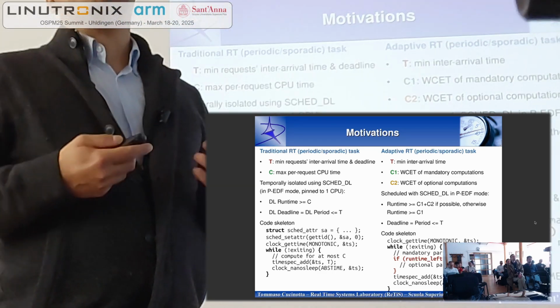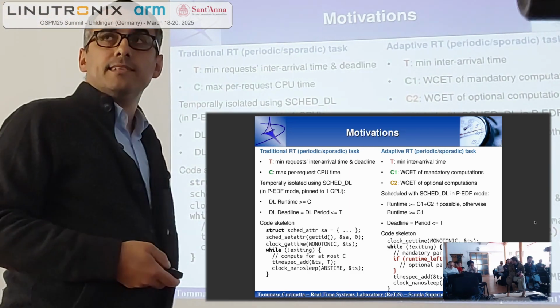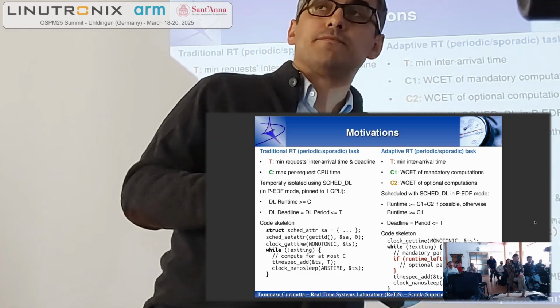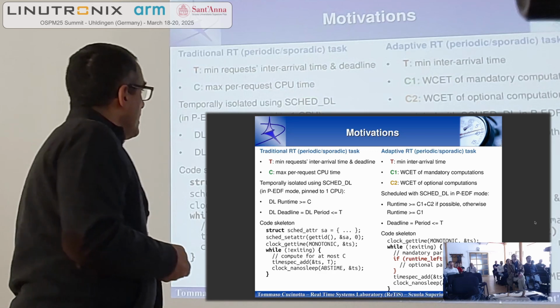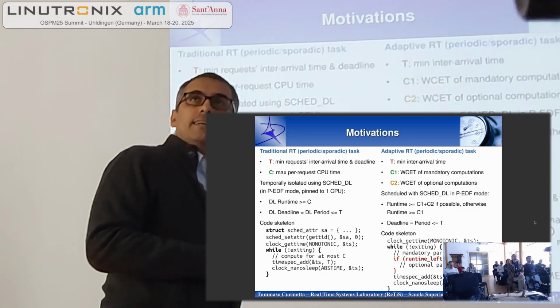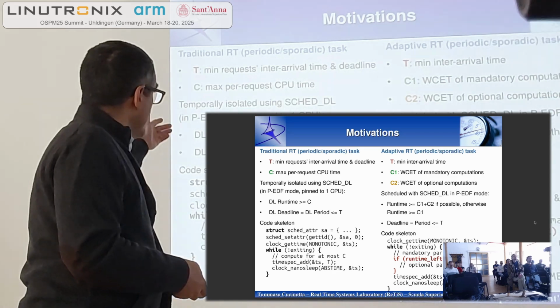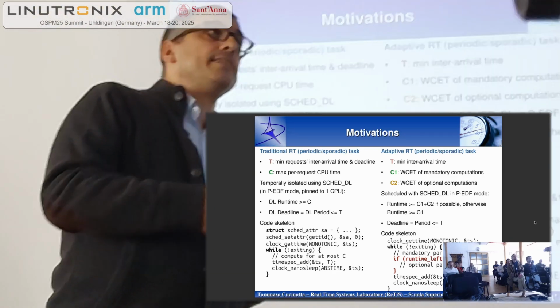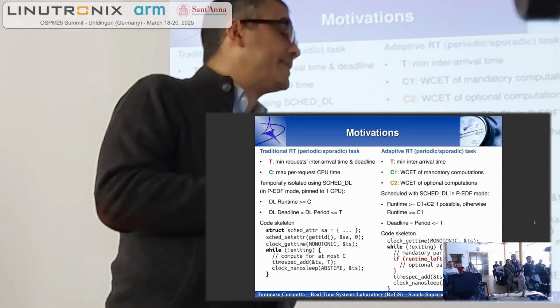This basically makes sure that every time this task is activated, all right, there are a few other catches. You need to partition your platform because global EDF doesn't really guarantee you much. But if you do things properly, you make sure that every time your task is activated, the kernel guarantees you your runtime on the CPU by the deadline, which is what you need to make sure you don't miss your deadline. Basic stuff.